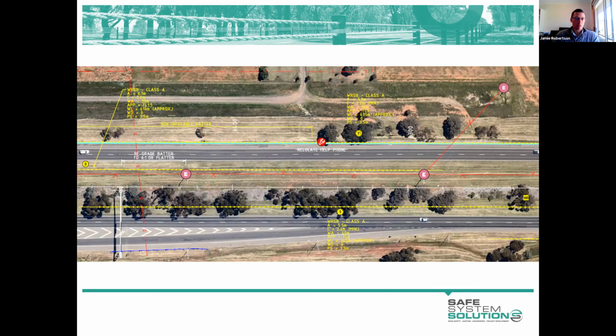So these days, and in fact, this piece of road has since been treated with continuous barriers, and it's been a bit of a challenge marrying up the two approaches. So this road now is generally fitted with continuous barriers at 3 to 4 metres on both sides. You will note if you look closely that the result of this sort of old approach was that you would end up with some weird and wonderful offsets to barriers.